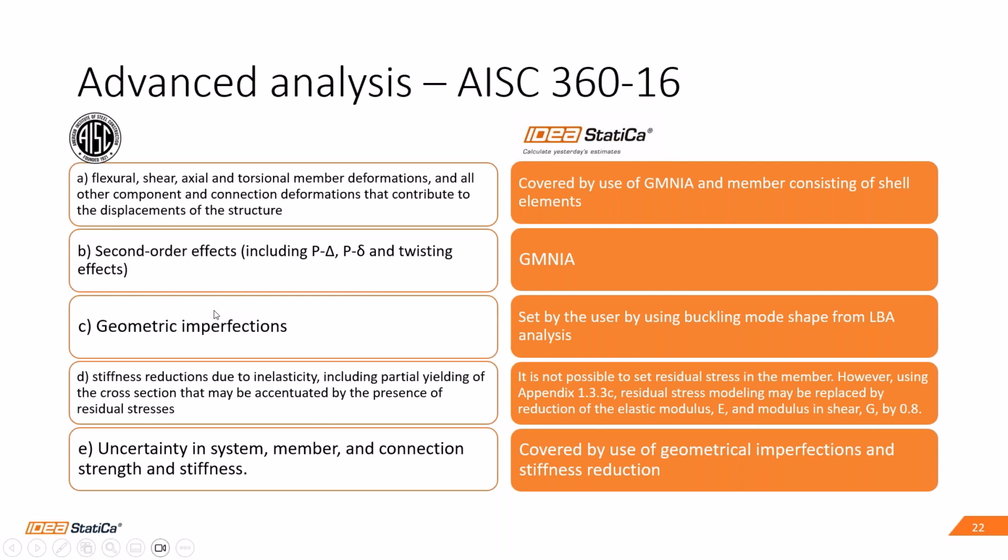Then the geometrical imperfections, you can set those by using the buckling mode shape, and then you can input those values over there. In this case it is asking you to consider the residual stresses. In IDEA StatiCa, it's not possible to set residual stress in the member.